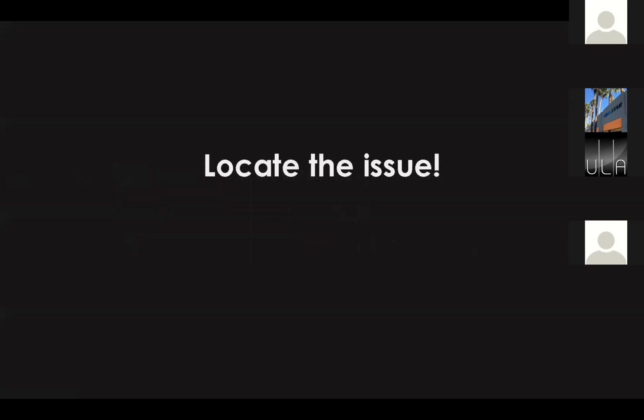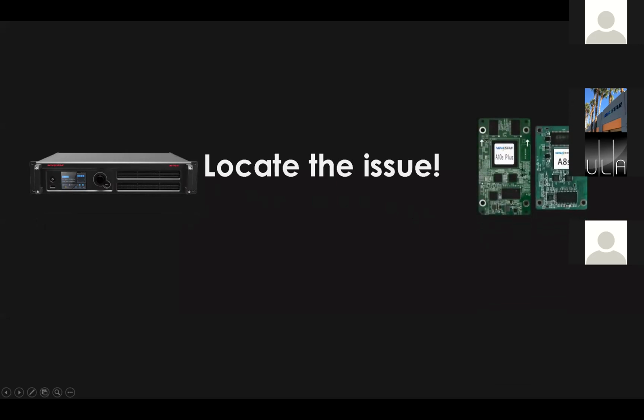I think for the first question, the most important part is that we should find out where the problem comes from. Positioning the problem is the key to solving the issue. The problem is happening either on the controller side, including video source, controller, HDMI cable, or on the receiving card side, including Ethernet cable, screen power, modules, and receiving cards. And the screen control function will help you locate the problem.